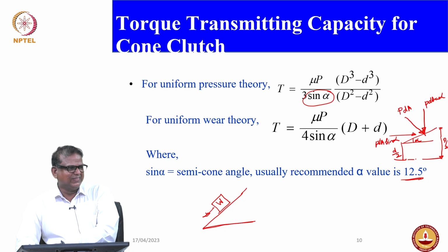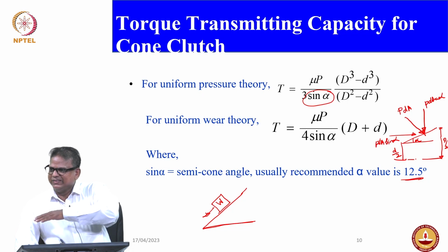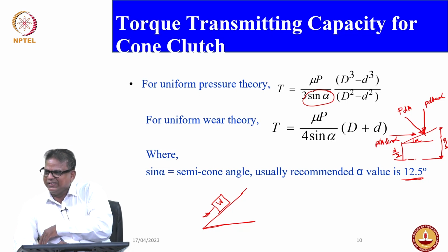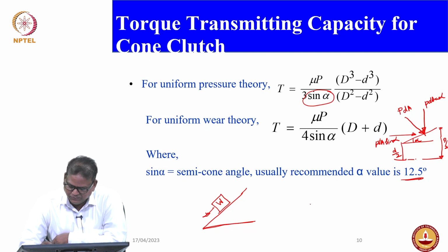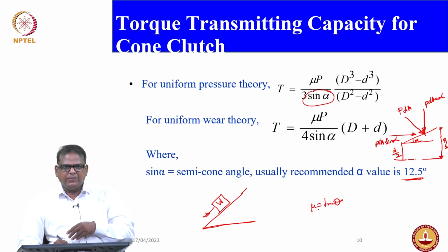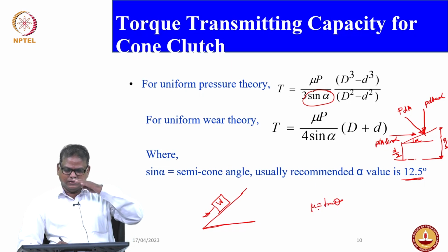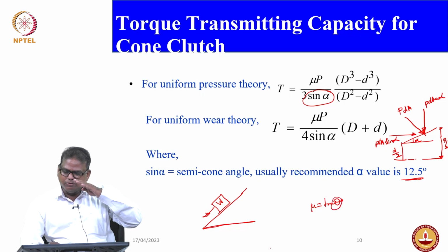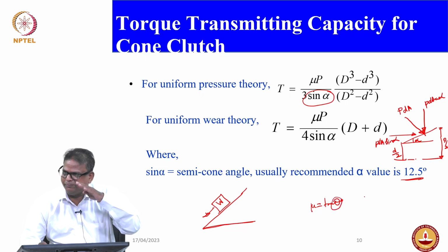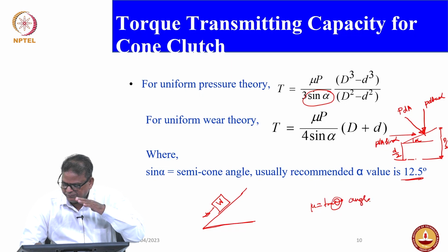Mu equal to tan theta, right? Mu equal to tan theta. That means the moment you increase it, theta is your angle of repose. It's called angle of repose.